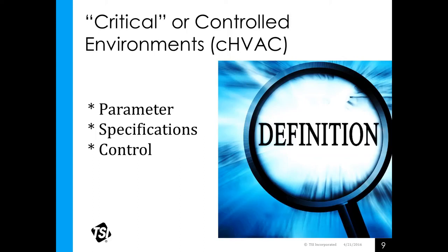On the critical side, there's a few more. There's another important parameter, dew point, and it's not just important for air conditioning calculations. Many critical environments rely on dew point. Environments such as data centers, semiconductor fabs, powdered pharma production, and packaging, powder coating processes, and all those. They rely on an accurate dew point measurement, and I stress an accurate dew point measurement because they're relying on that for total control.